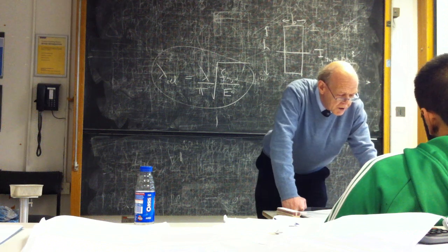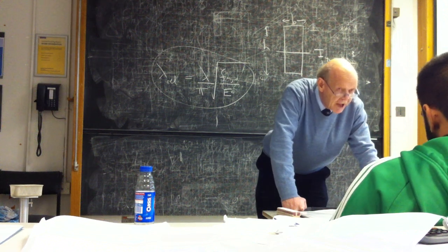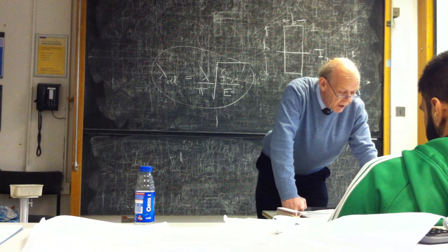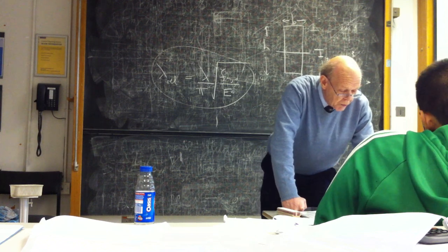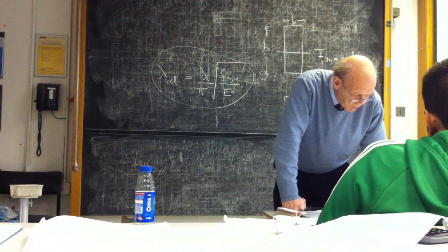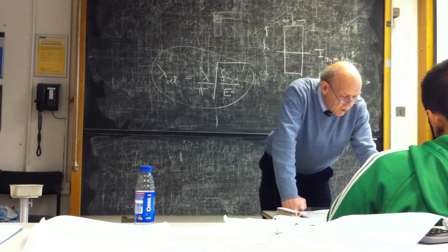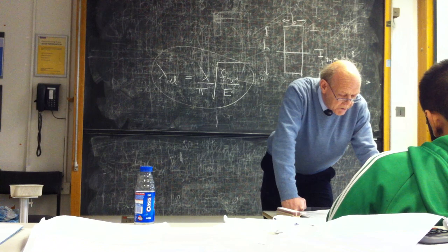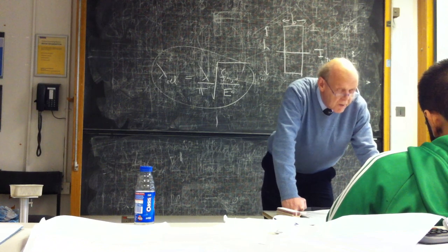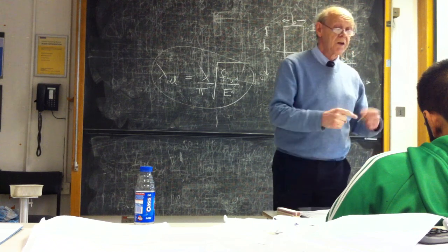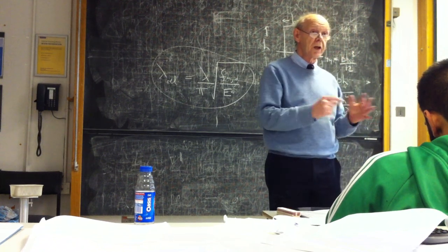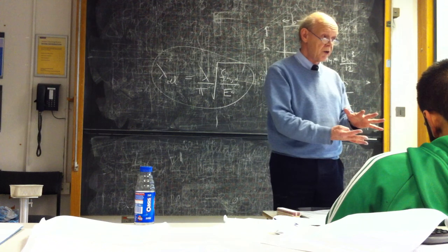So I've worked out things for both the YY axis and the ZZ axis, and I've worked out the relative stiffnesses about both. Now the point is that if you're looking at the top of page 30, the relative Y stiffness is 0.94, the relative Z stiffness is about 0.98. Both of them are greater than 0.3, which is the criterion that the code uses to say, well, buckling is going to be more of a problem than just squashing material flat.